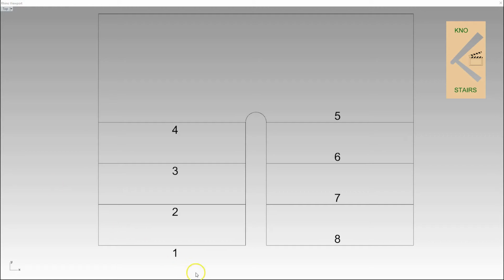We'll drop some numbers on here so we can see where our goings are. The dims for the going, again here, are 254mm or 10 inches, and I haven't drawn in the nosings and risers. Obviously if they were drawn in, you'd have a nosing along the front of the tread and returning back, with the spindles set over the tread, and the centre line of the spindles is where our handrail is going to run. But we don't need those, so we'll get rid of those again.